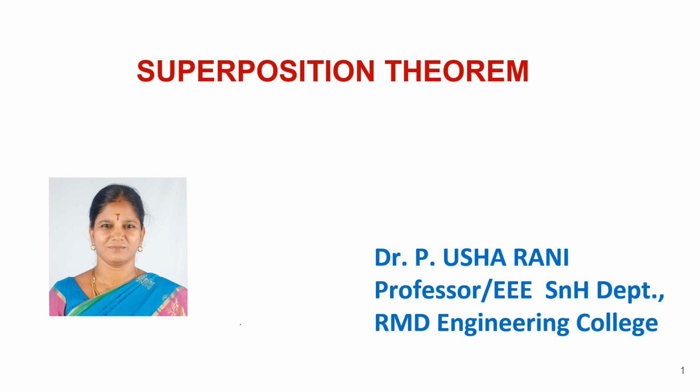I am going to brief about the topic of superposition theorem. The general principle is to determine the effect of several energy sources, that is voltage sources or current sources, acting simultaneously in a circuit by considering the effect of each source acting alone, and then we can combine, that is, we can superimpose these effects. That is the superposition theorem.